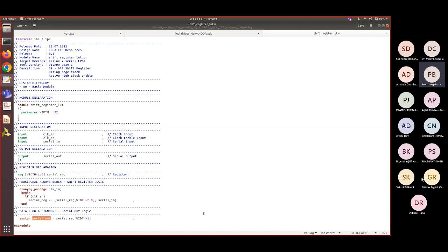That is not correct as per the behavior of the design, because it has to follow the behavior of my RTL code. Yes, width minus 2. So total we get only 32-bit shifting, but in that, 2 flip-flops are utilized for 2-bit shift, and the 30-bit shift will be done by the LUT. One LUT can do this, because it can do up to 32 bits maximum.